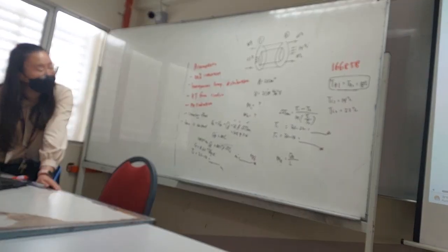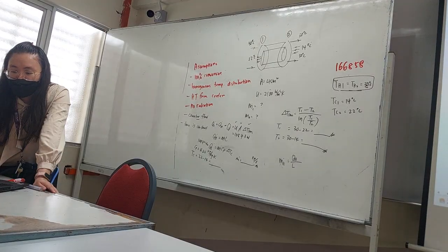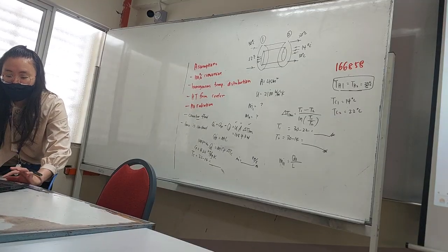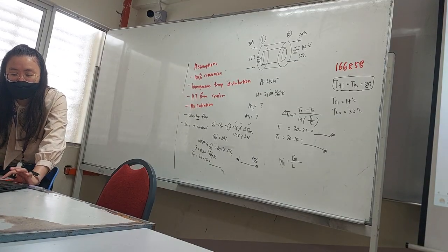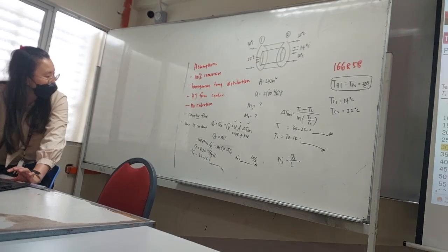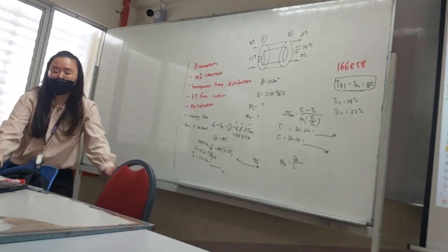Okay, you need to refer to appendix table A9, because if you look at the previous one, they gave you 100 degrees Celsius. Now the inlet temperature is 31, so you are going to look at this. You find the enthalpy of vaporization, so the L value is 2431.